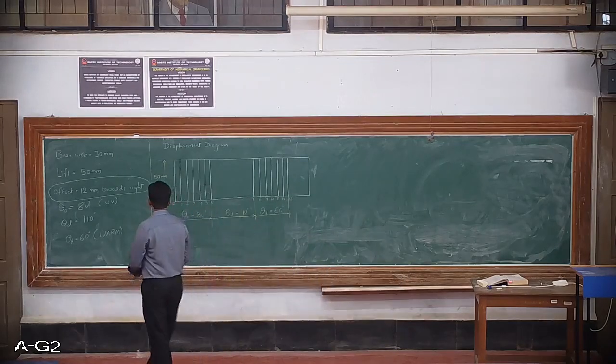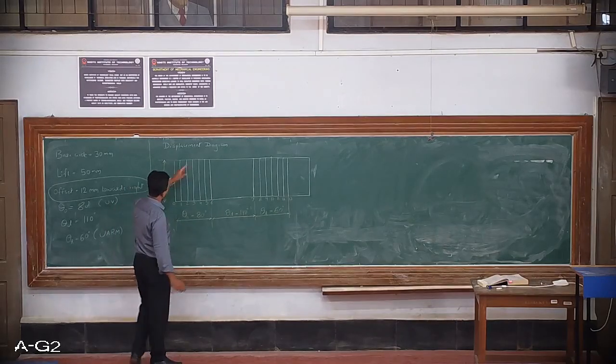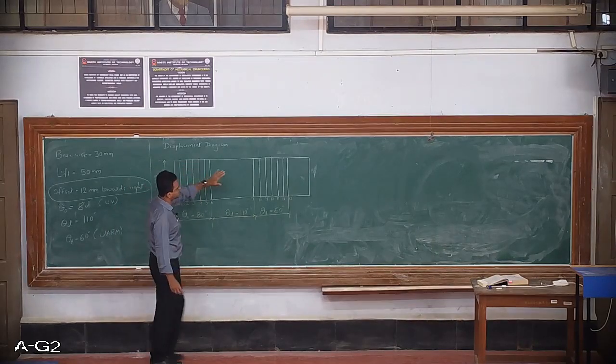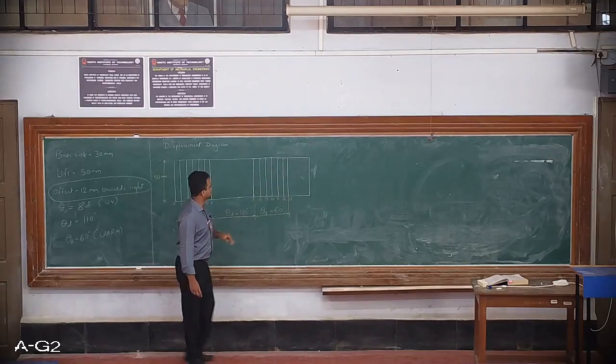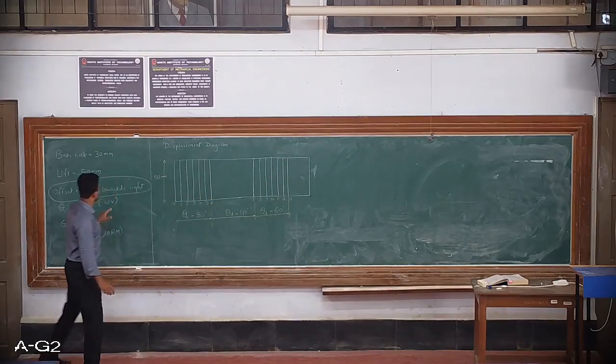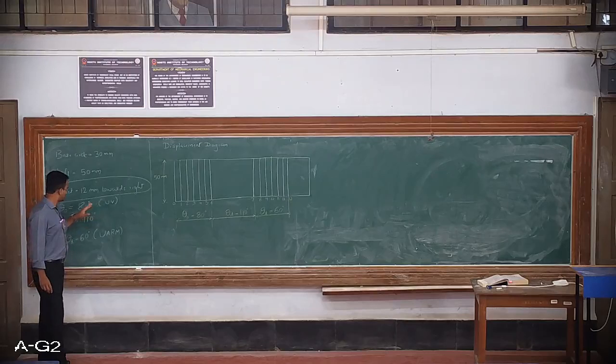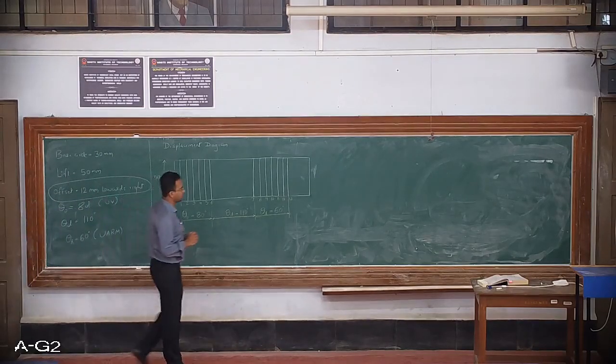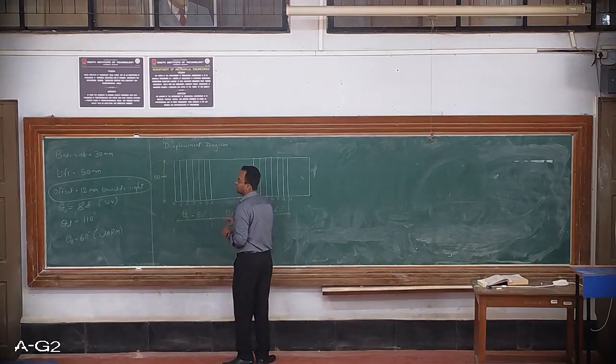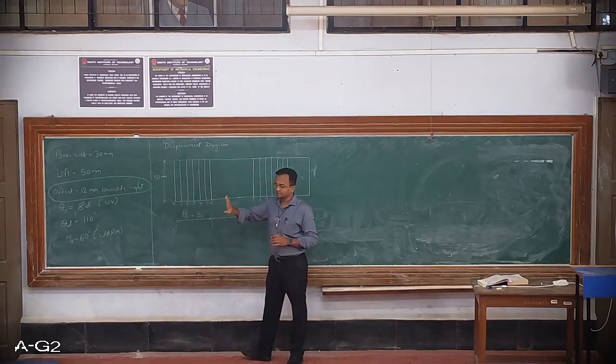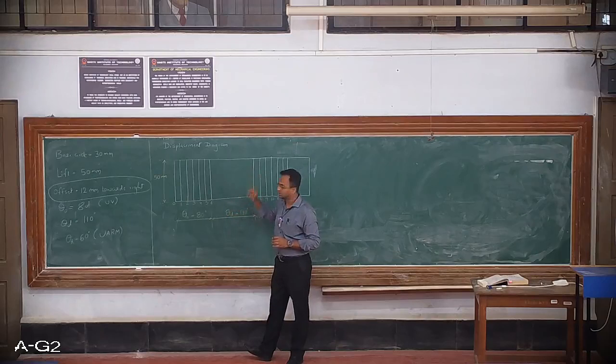Now in the next step, we need to draw the displacement curve here for the rise stroke and displacement curve here for the return stroke, depending upon what type of motion it is having. So for rise stroke, it is having uniform velocity. So we have discussed in the previous class, for uniform velocity, all you have to do is just draw a straight line from start to the end point.